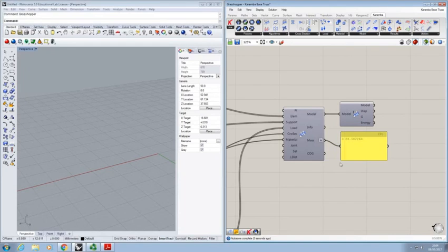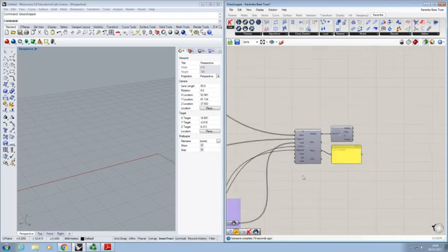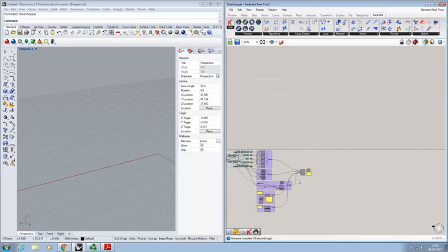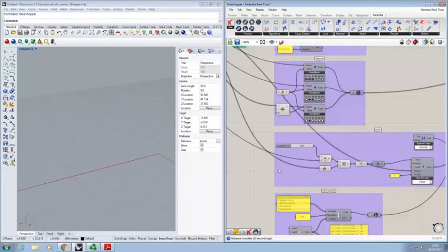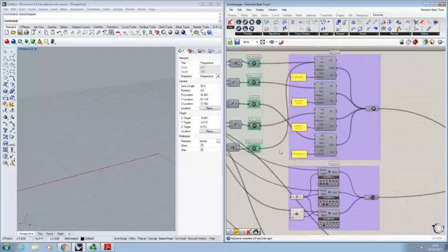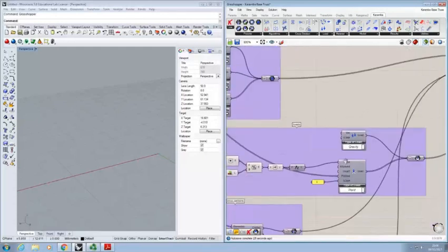Karamba, one important thing that I missed at the beginning, is that Karamba works in SI units generally, but not always. Some of the inputs are set up in a way that you can't change the units, and the only way to know what you're inputting is either it doesn't run very well, or just hover over things and it'll tell you what unit is expecting.